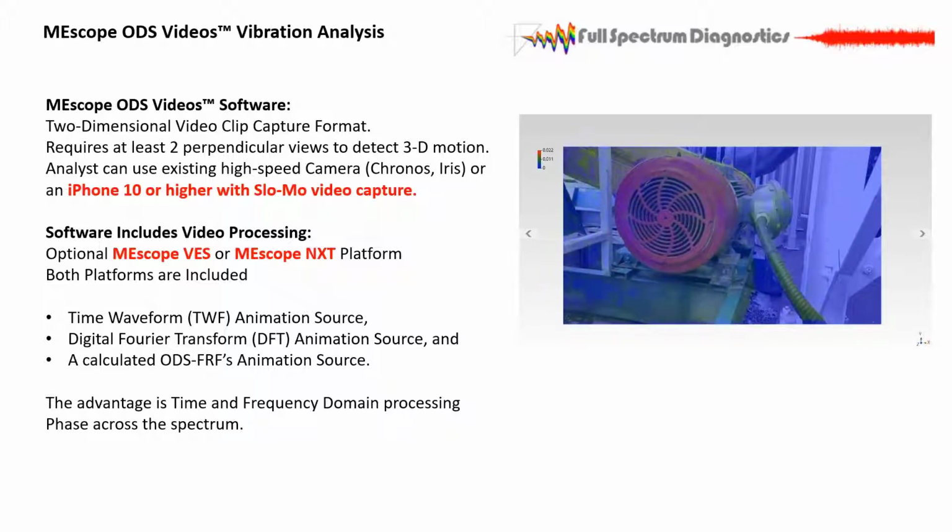The accelerometer data is three-dimensional. We're taking X, Y, and Z measurements simultaneously. And when we do a bunch of measurement grids to get a good idea of how the frame's moving, how the motor's moving, how the fan's supported, then we will be able to see that three-dimensional response and be able to rotate it around and see what's really going on.